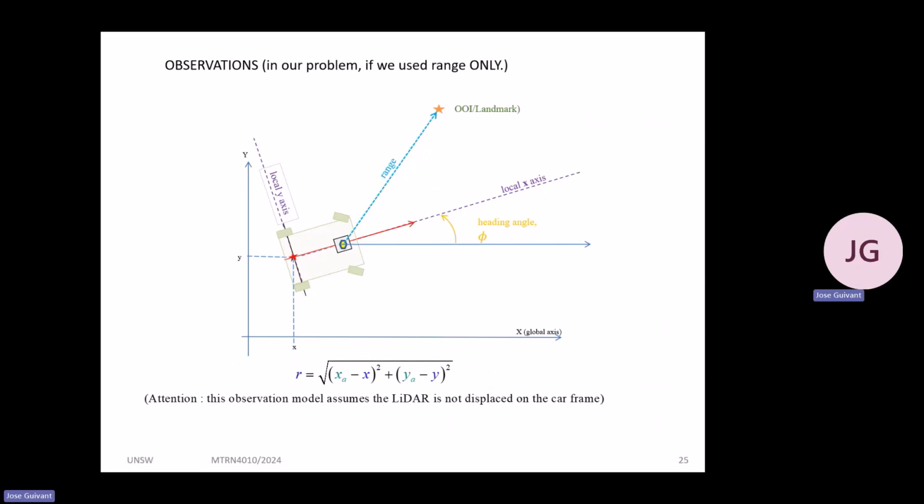And then we say, okay, what happens in our project in part A1? Well, your observation function or your output equation will be this, which is perfectly a function of the state of the system and some variable which we do measure, which is going to be the distance between the LiDAR sensor and the position of the object of interest. And I repeat, because now we are assuming that this sensor is exactly at 0, 0 of our car, this is perfectly correct. If you had this with certain displacement, this equation would change. You are trying to represent the X and Y position of the car in the global coordinate frame using that convention in which we are modeling this point of the car.